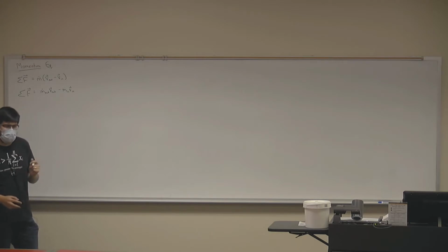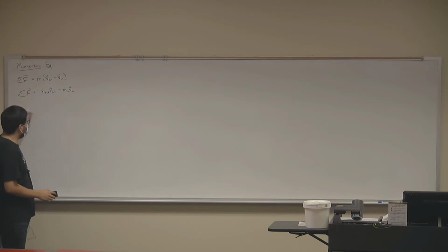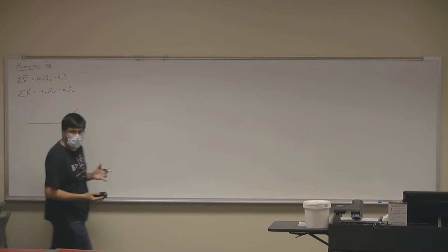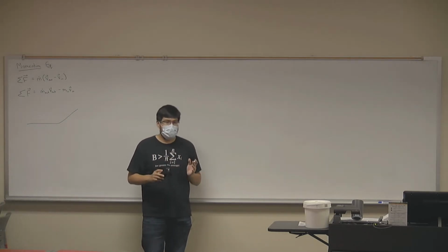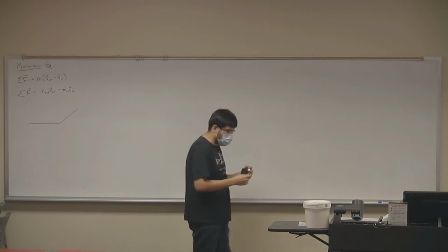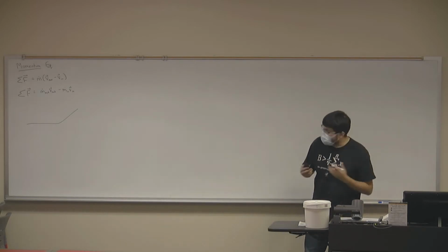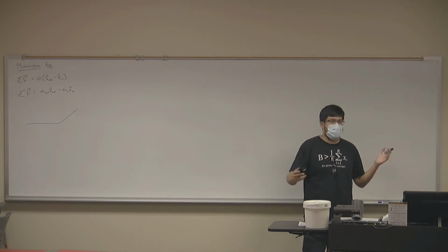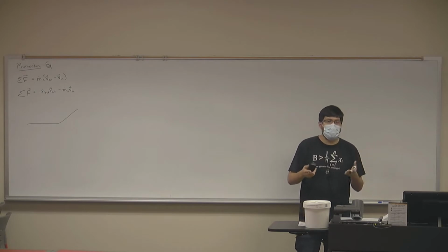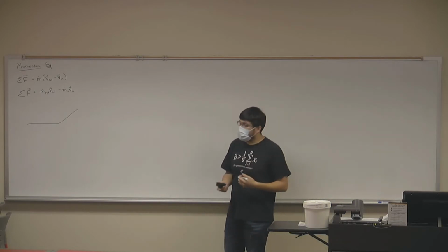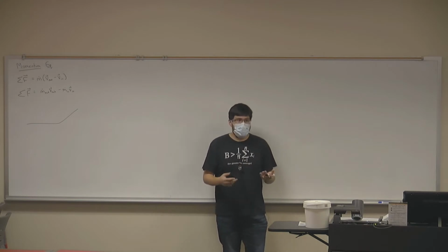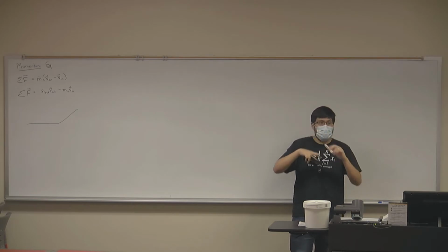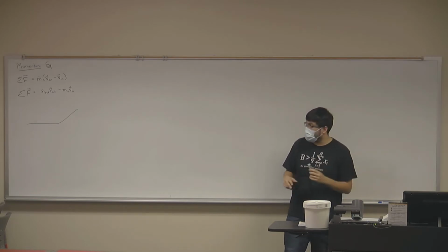During the last 5 minutes of Monday's class, we applied this momentum equation to the case of deflectors. We define deflectors as any solid structure that deflects, that means changes the direction of flow. And we said that we can find deflectors pretty much anywhere. At the smallest level, we talked about a spoon, right? You open your faucet, it hits your spoon, it splashes water everywhere, because the spoon is a deflector that changes the direction of your flow. At the larger level, you have your car's windshield, right? Your car is moving, air is a fluid, so the windshield changes or deflects the direction of air particles as they travel past your car.